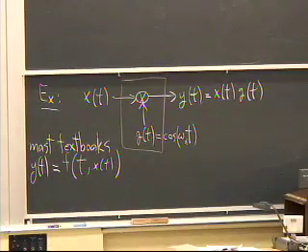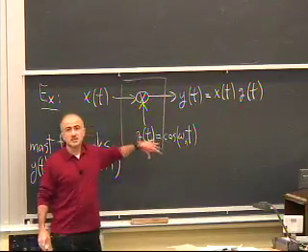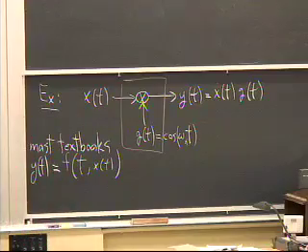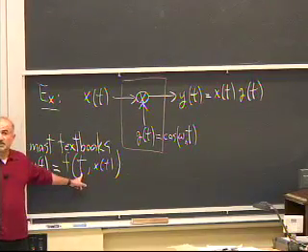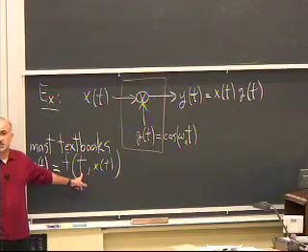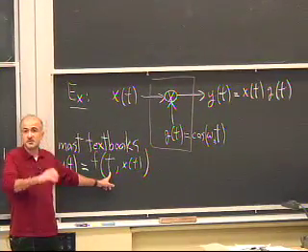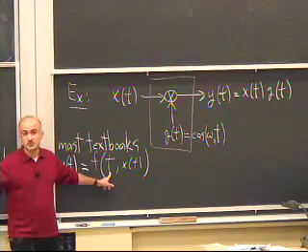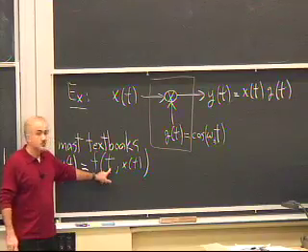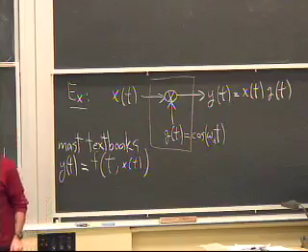But our strict definition of memorylessness imposes the condition that you cannot have any memory elements inside this box. You just can't. You can't have an oscillator in there, because an oscillator requires keeping track of time. Notice this system keeps track of time. And if you have to keep track of time, you can't do that without memory. You have to have some stored information about what the time origin is, and then you count. But a memoryless system cannot have that. And that's why we insist on this particular definition.